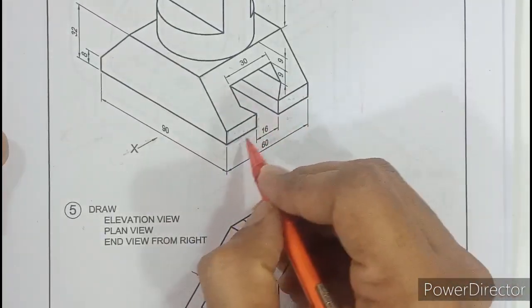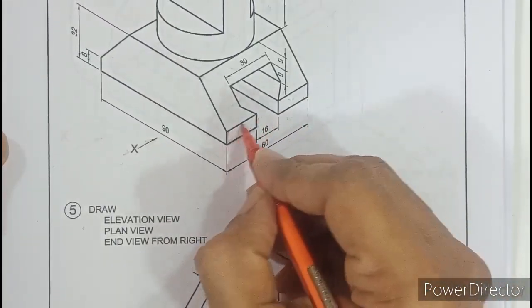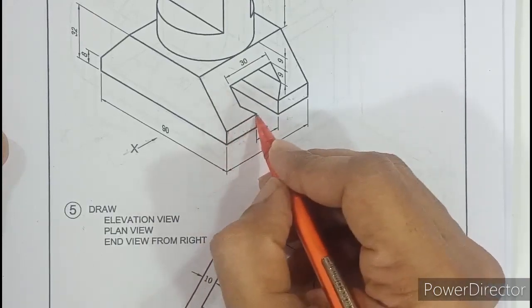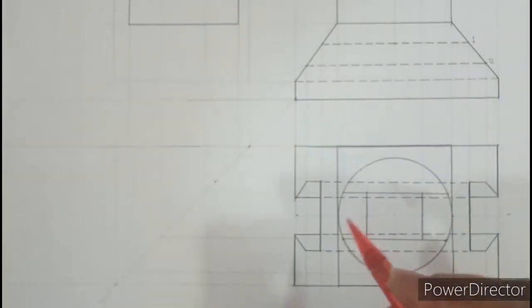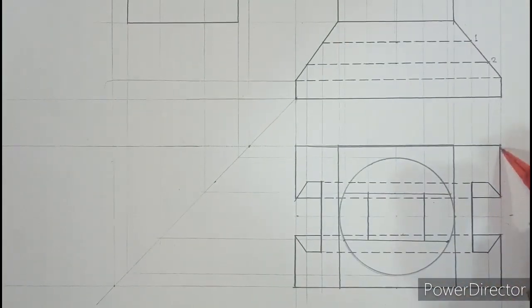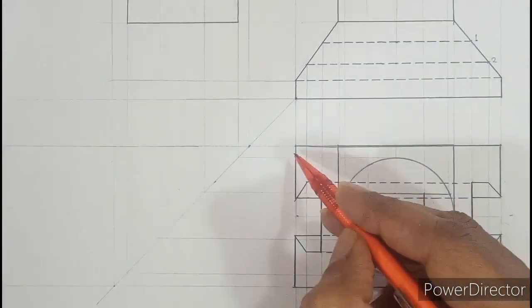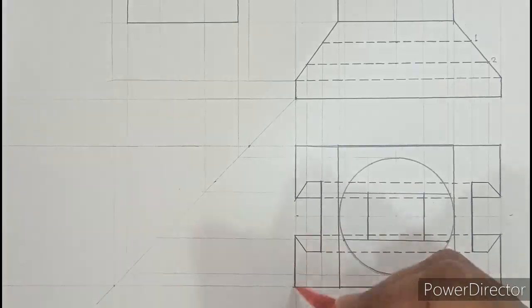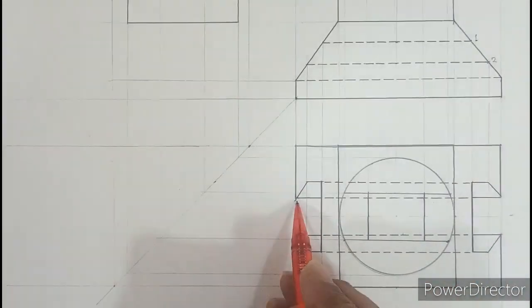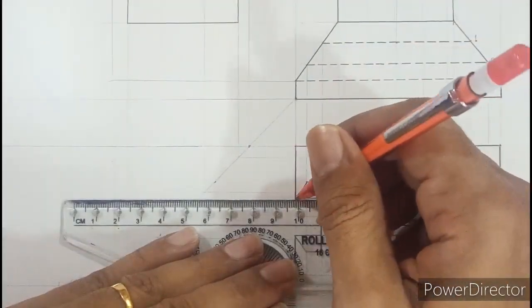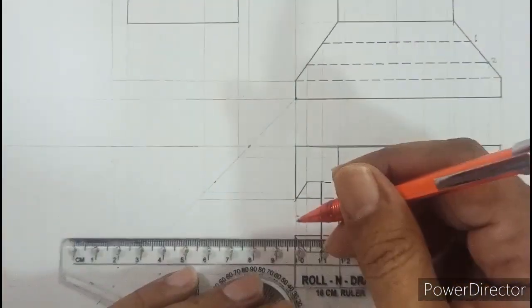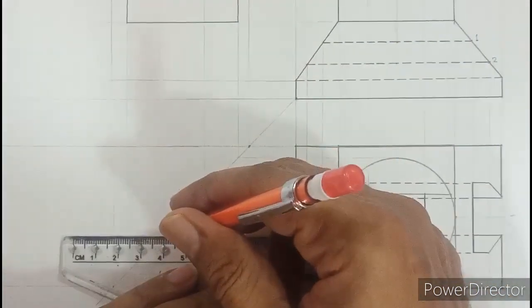To learn orthographic, you should be able to identify where the same width you have drawn in the top view is. In the top view, that same width is this edge. You have left 16 in between, and this is the same edge, or you can say it is this one, or this one. I need to project this in between 16 in the side view. From here, I get this little down and extend till the 45-degree line, correct?